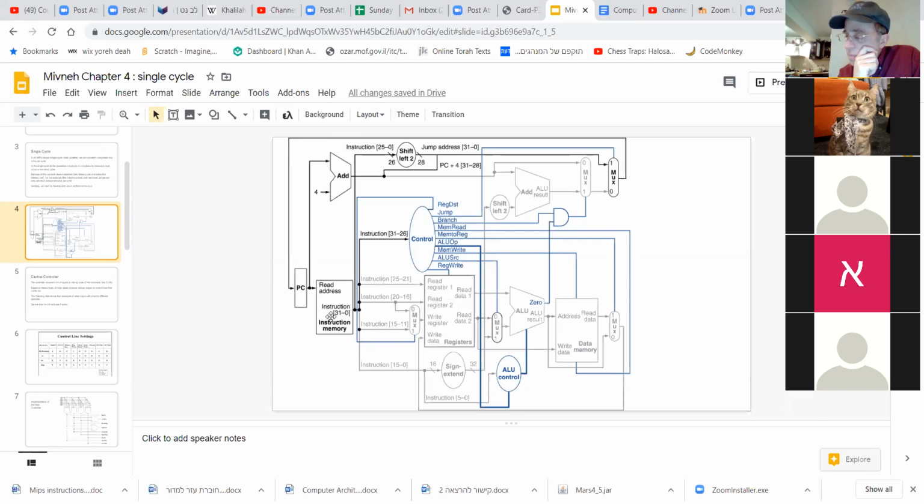Essentially, if you think about it, ultimately there's a wire going from this output line, these 32 bits of output line ultimately are connected to every single group of 32 bits. In other words, every 4 bytes of memory are directly connected to this output line. So I simply have to tell, back to what we talked about before about the ands and the zeros, the 0 and the 1, and doing an and, all I have to do is essentially block out everybody except for the one I want.